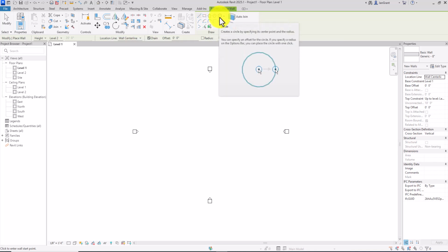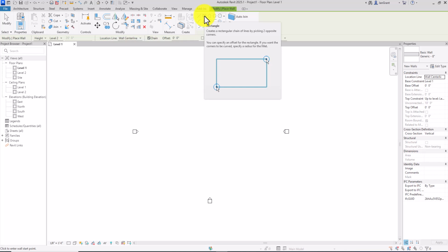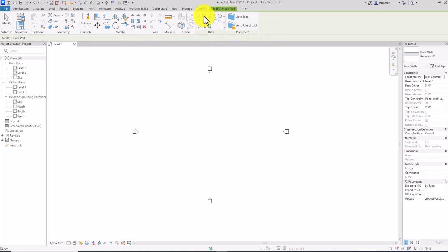And so what we're going to start with is something basic. Instead of using lines, we're going to very quickly draw this rectangle. We're going to draw a building with the rectangle. So let's go ahead and click on rectangle. And now it doesn't matter what size, everyone will have a different size. We're going to be able to modify it as we move forward.